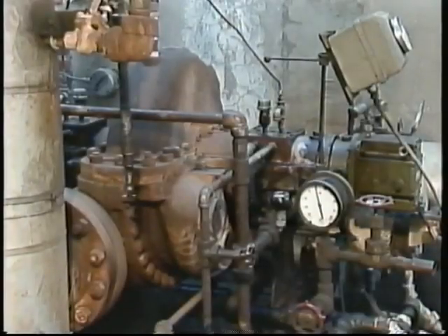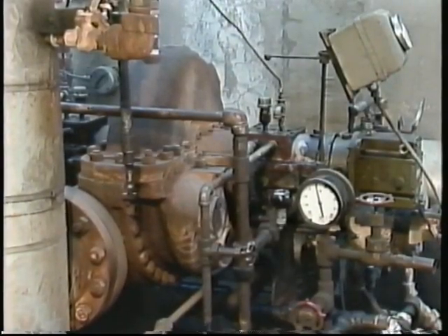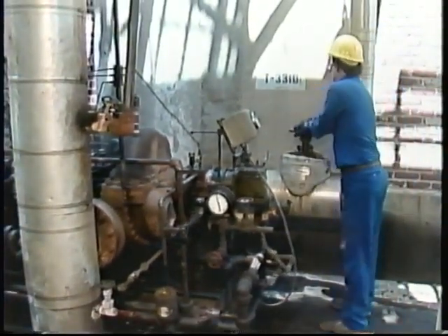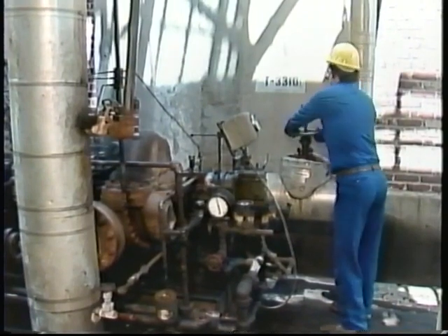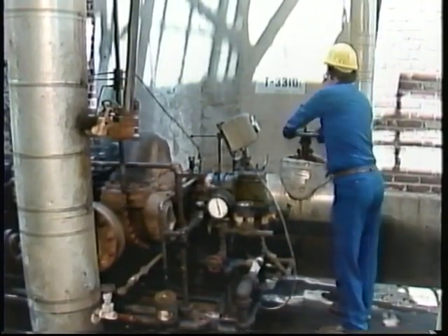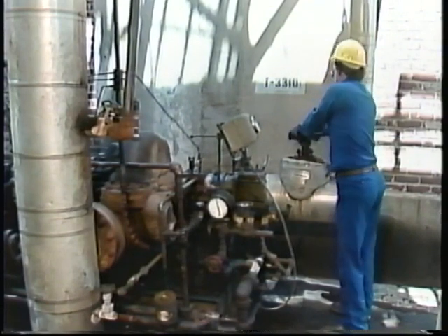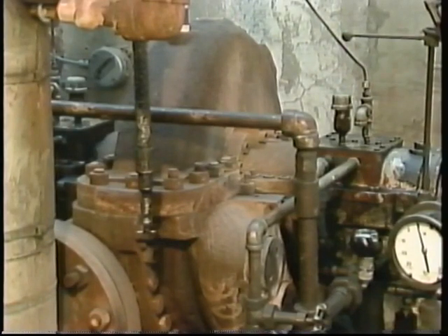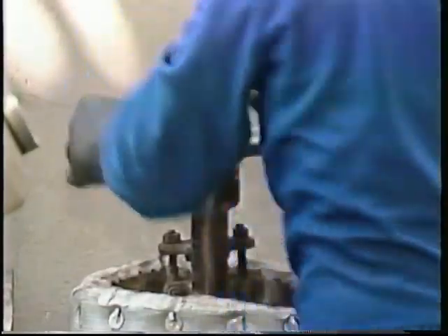Now, not all turbines are shut down using the manual trip. In fact, the trip lever isn't used at all to shut down this particular turbine. Instead, the operator begins gradually shutting the turbine down by partially closing the throttle valve and bringing the turbine to a slow roll. He lets the turbine rotate slowly like this for a brief period, specified in his facility's operating procedures, typically 2 or 3 minutes. This provides a cool-down period for the turbine.